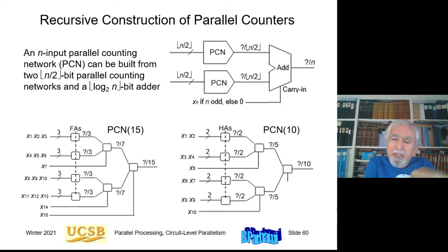Okay, so this recursive circuit has an advantage that basically leads to a tree structure, and it is fairly regular in design, so that, for example, you lay out this part of the circuit, and this part of the circuit is identical. You just repeat that layout.